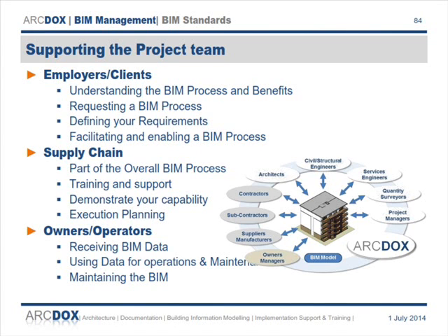And then over the course of the project, once the building's handed over, the building doesn't stay the same over its entire 30-year life. It does change, things happen, things get knocked down, rebuilt. The BIM is only any use to anybody if it's up to date. So there's an exercise there in the FM stage of the project in ensuring that the BIM is kept up to date. If people are doing work on a building, they need to take the BIM model, use it, update it, and give back the updated BIM model.